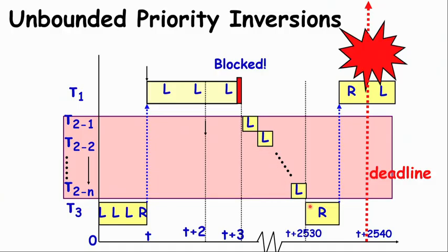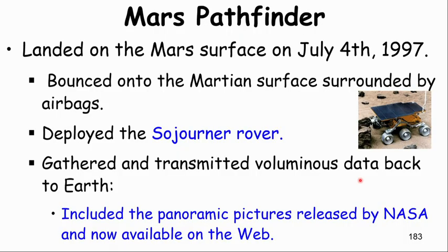and T1 keeps on waiting for T3 to be able to get the CPU and complete its execution, but by that time T1 misses its deadline. So, there is application failure. Unless the unbounded priority inversion problem is handled adequately, a real time application can fail.